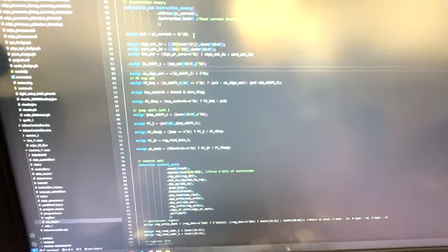And then we have all of these programs that are doing the program counter. These are the things I was talking about, where some things like branching, jumping, and stepping will take different amounts of time, and therefore we will jump them in different ways. This is also where we do sign extension and zero extension, which are necessary to make sure that we fit in our 32-bit wide buses. This is also where we are extracting various jump locations and our branch locations.